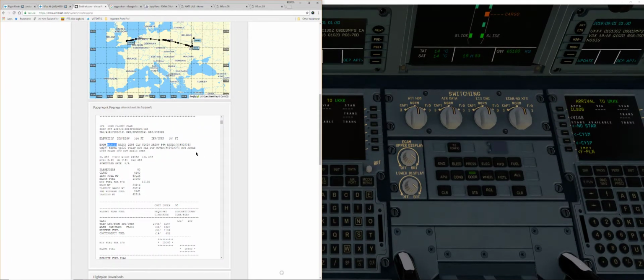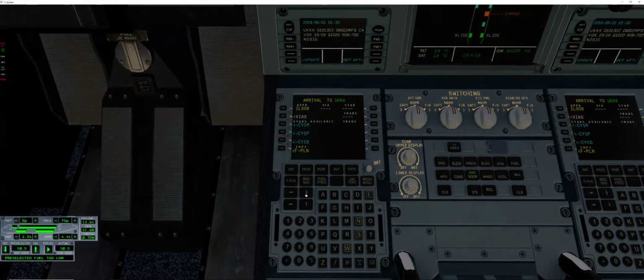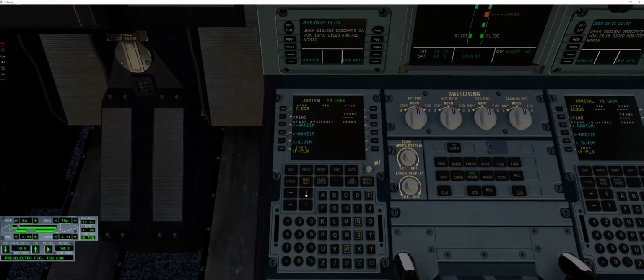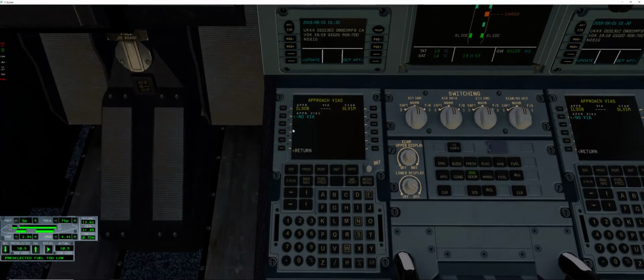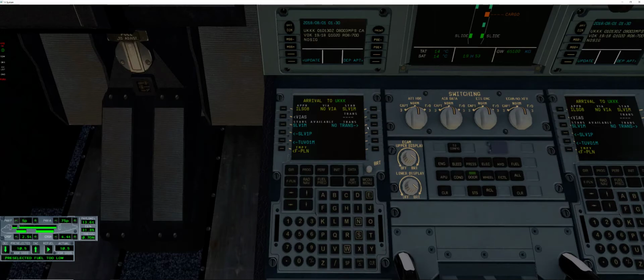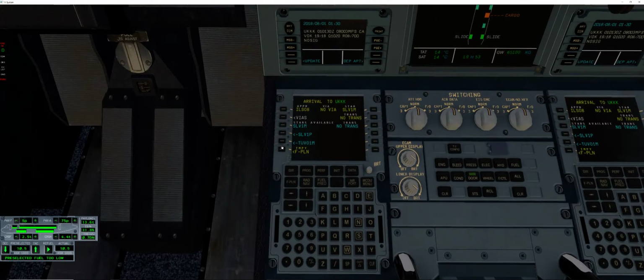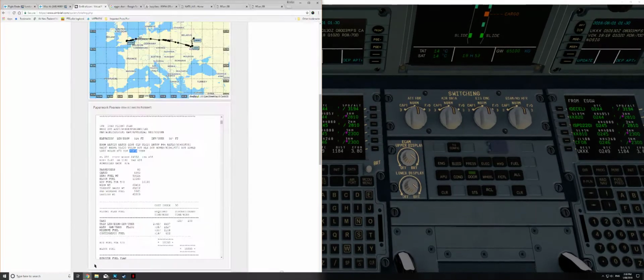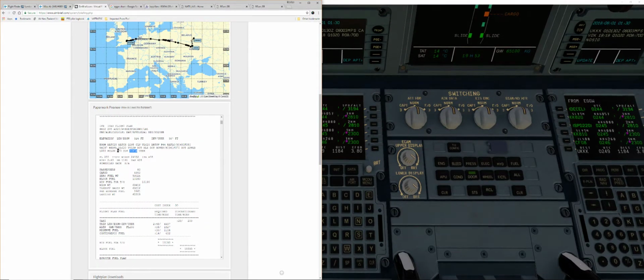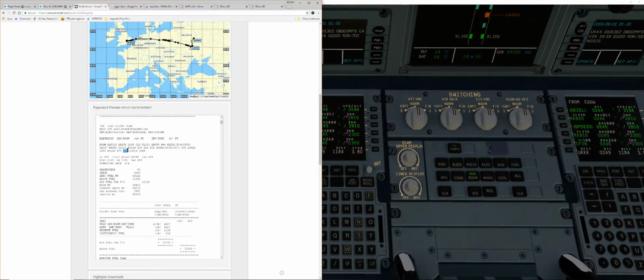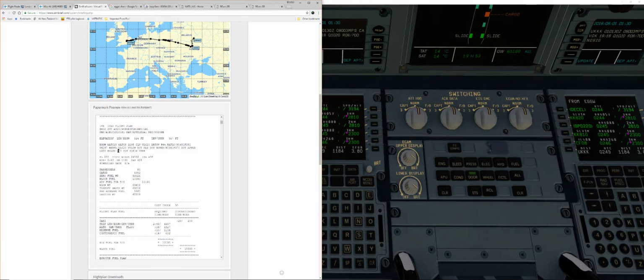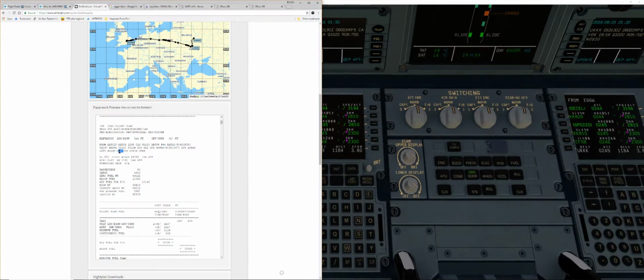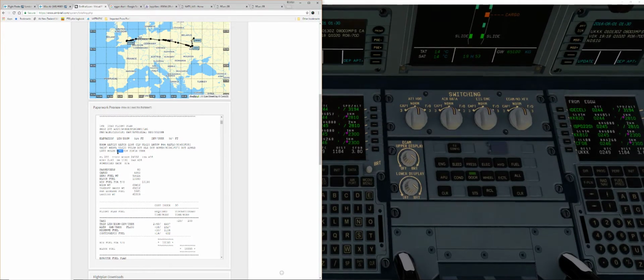And we have the SLB1 MIC arrival. That's the one. No via, no transition. If there is, you can find it over here, which is just before the STAR arrival. That will be your transition if there is any, but that is not the transition, that is a route.